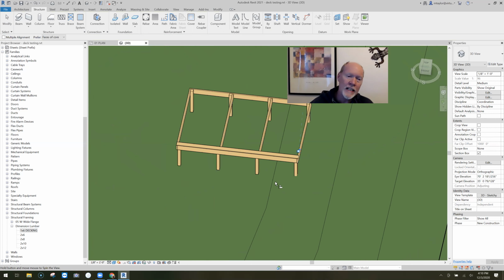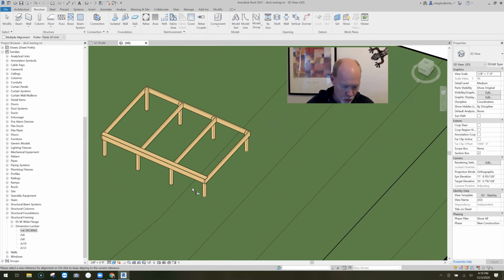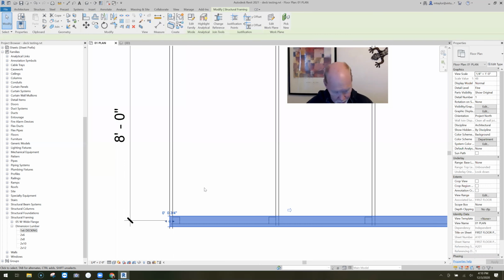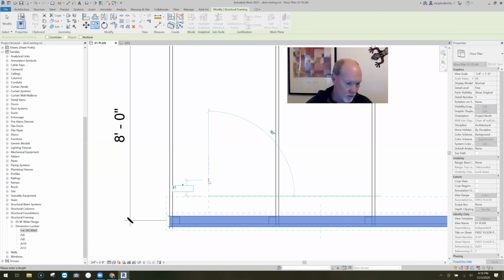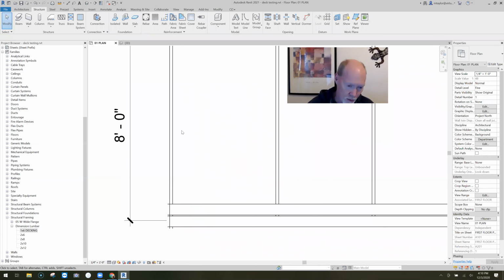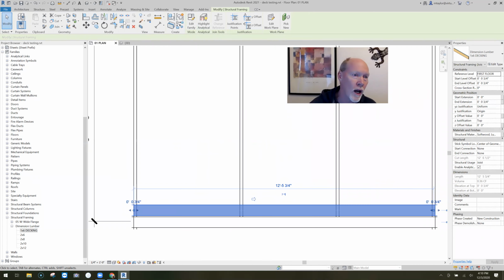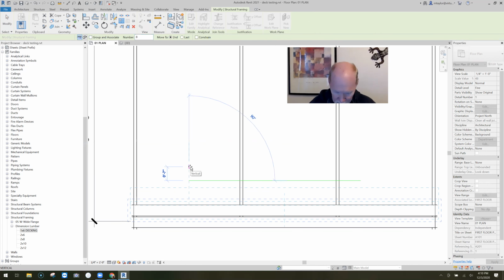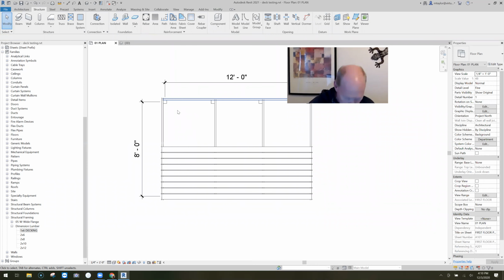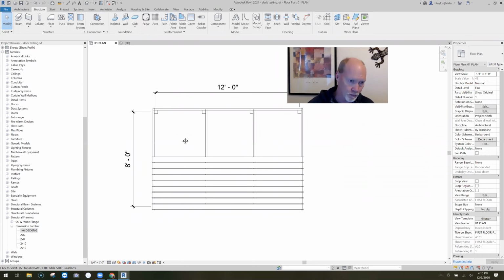Okay. Now, I don't want to put these boards in this way, one at a time. It could be tedious. I got one. I can copy it. Look at this. I can copy it up 6 inches. Looking good. I can array it. Watch. Click on it. Use array. And I'm going to disassociate it. I want 8 of them. Okay. And I want to point up and say every 6 inches. Boom. And so you can get your deck boards in that way. That's one way to do it.